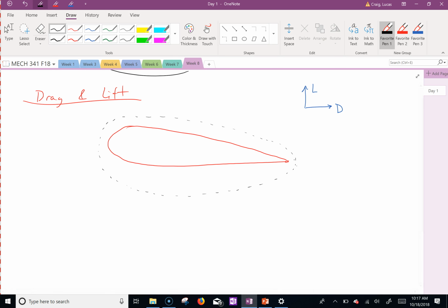And that's actually how we get the lift, because you have higher pressure pushing on the bottom compared to the top, okay? And what we can do is everywhere we draw these lines perpendicular to the surface. And they're pressure, right? Pressure acts perpendicular to the surface, normal. So those are pressure. And I'll do one up front.